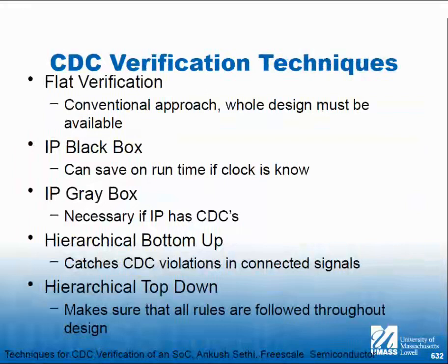Flat verification. You read the code. This is an option for white box testing. So if there's a clock domain crossing, a verification engineer goes into the code and verifies that the transfer between those clock domains looks like the picture I just showed you. An output clock, 2 clocks going in.